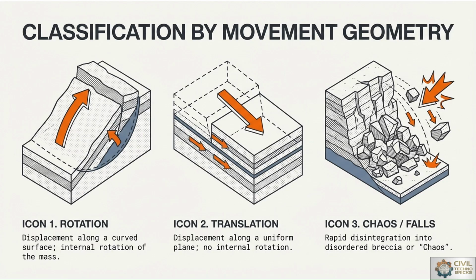In the third, chaos theory, or we can say the fragmentation of the rocks, represents a catastrophic stage of slope failure, where the internal arrangement of moving blocks becomes entirely confused and distorted. High vertical cliff faces with dense intersecting joint networks are prone to sudden failure or explosion of the rock due to gravitational forces.